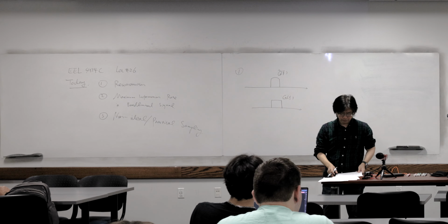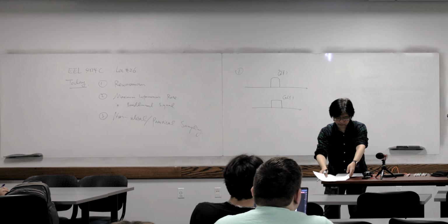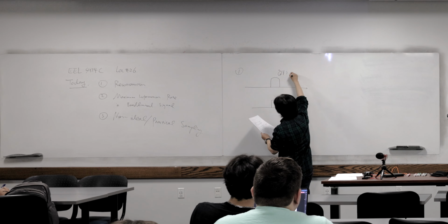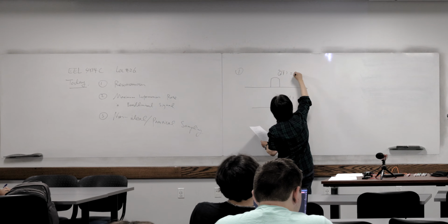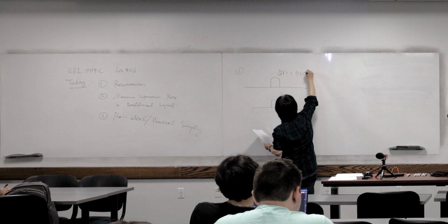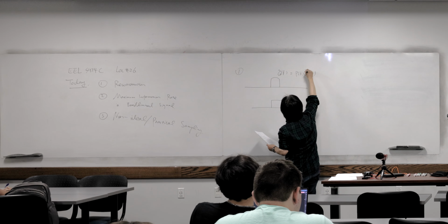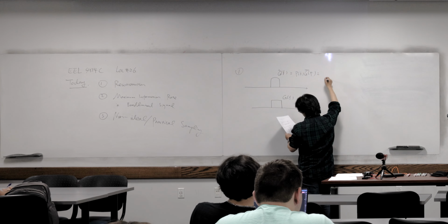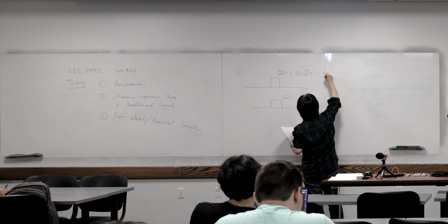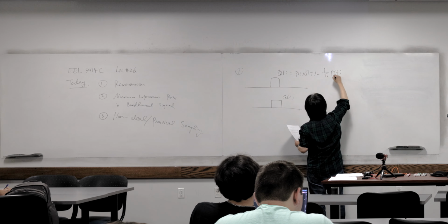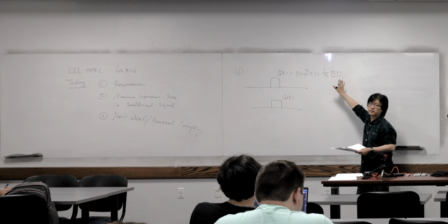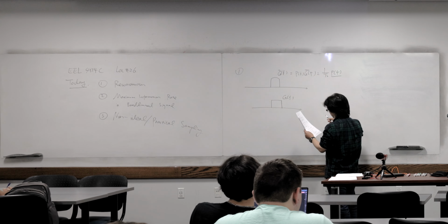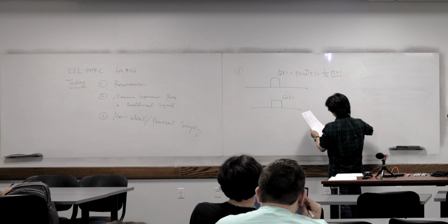Okay, so maybe let me write down what G tilde of f equals. This guy equals nothing but P(f) multiplied by G bar(f), where G bar(f) is the impulse sampled signal. If we write it out, it will be 1 over Ts, and P(f), where P(f) is the reconstruction pulse shape, right?